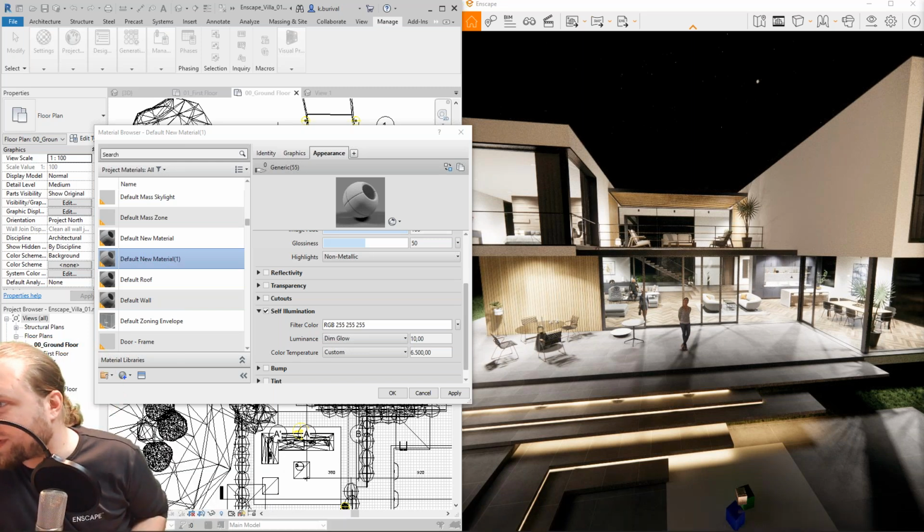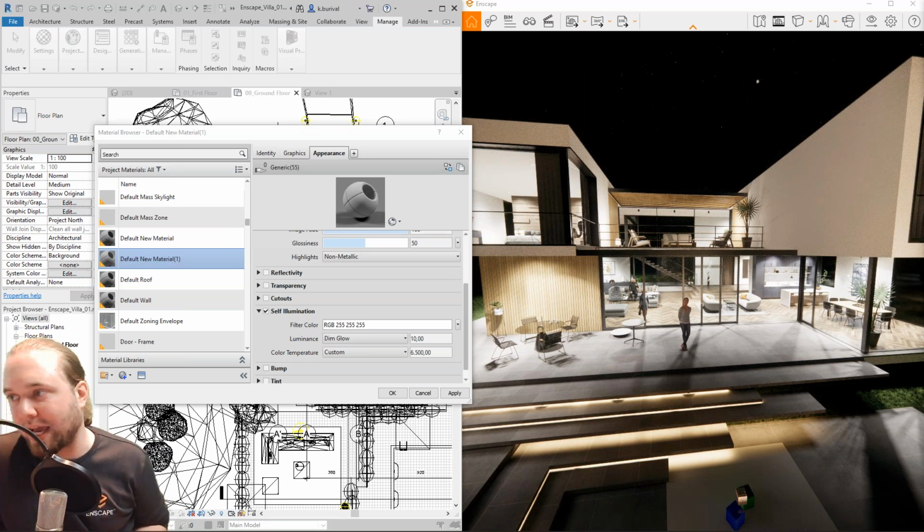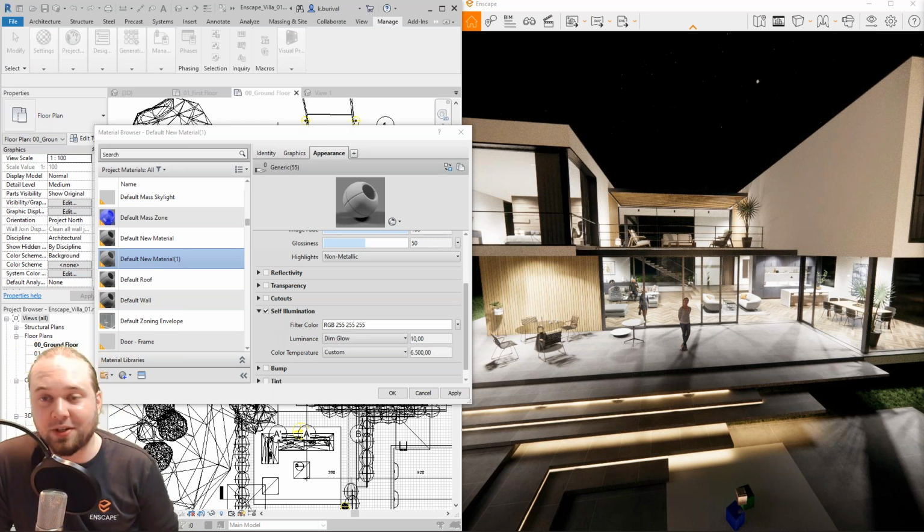Can you rename the materials in this window? No, you can't. You have to rename them in the design application they came from, or in Revit, otherwise they won't show up. That could be a feature request if you can tell us why you would need to rename the materials in there. Why are you getting black shadows reflections on the green metallic material?